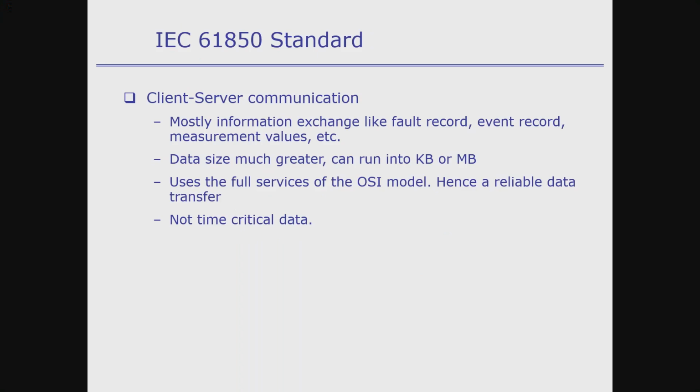The sampling rate will depend on the particular network, or it will depend upon the voltage data. So you have the distribution system, and if a fault takes place, you are doing the switching action. The repercussion of a wrong switching action is far more serious, but if it is some small mistake, the aftereffect will not be as severe. So in that case, the sampling rate is uniform for the standard, but depending on the level, you will have different sampling. So it will depend on your device itself, on your IED, for example.